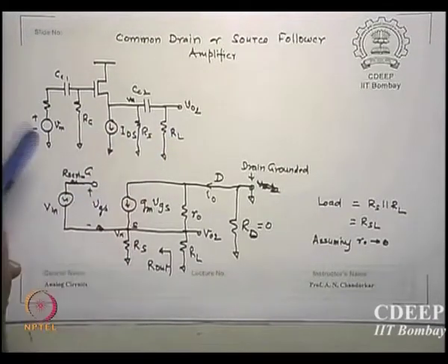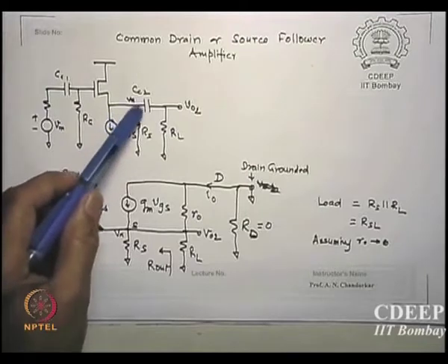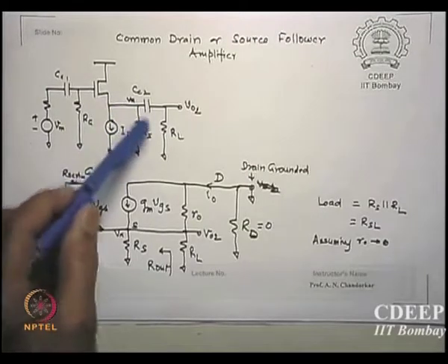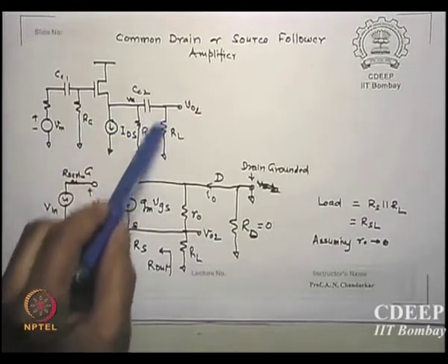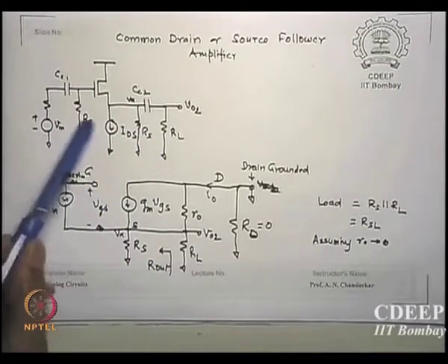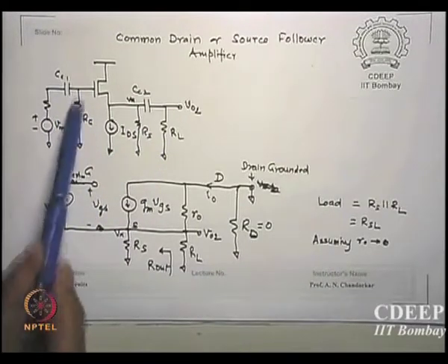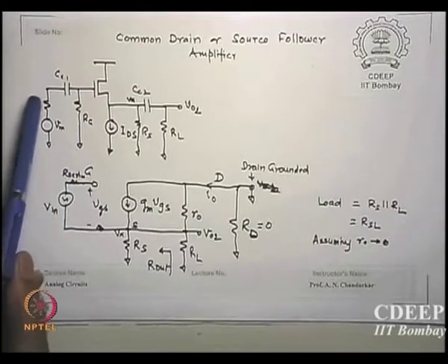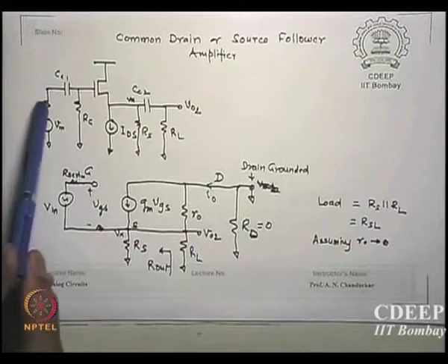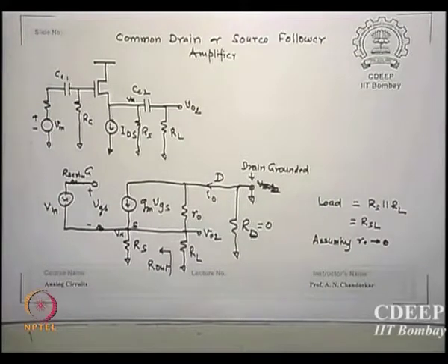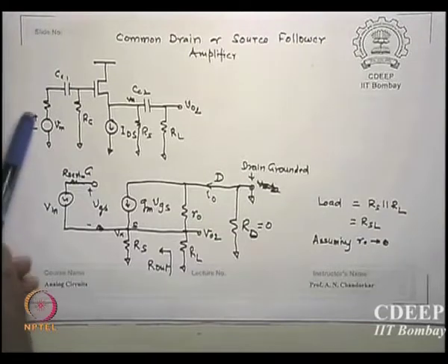This is that source resistance RS, and this is the additional load resistance if it is there. This is that RG, which is the bias equivalent resistor RG1 parallel RG2. This is your signal source, R signal or R series, whatever you call it. That word source is common here, in the sense of signal source resistance.